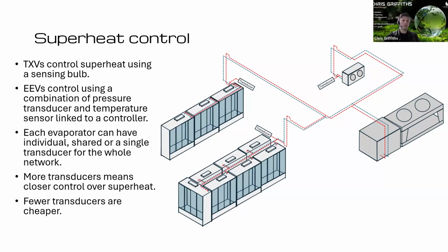So at that point, you can almost group similar cabinets with a single pressure transducer. On the schematic we have here, we have a transducer on 3 cabinets, another one shared between 7, and then one for a cold room. They could all be spread out 200 feet apart, but it gives that closer control about that localized pipework.